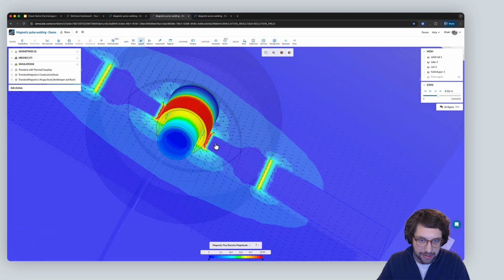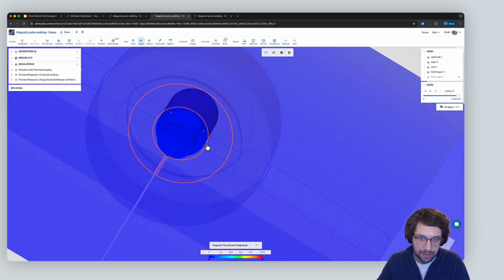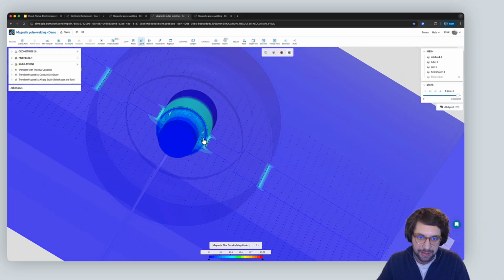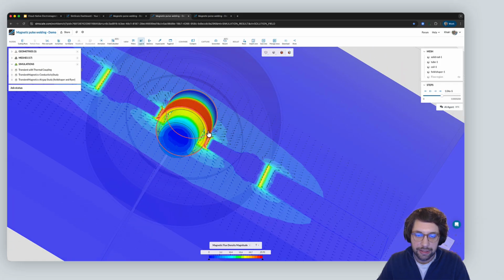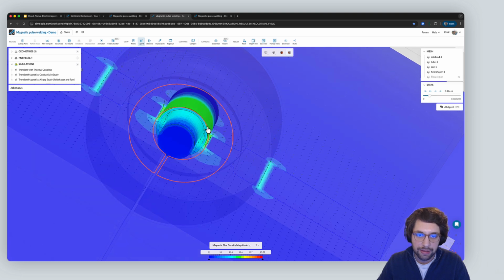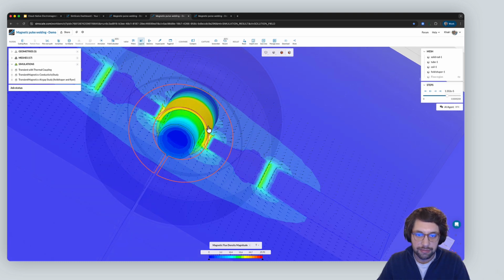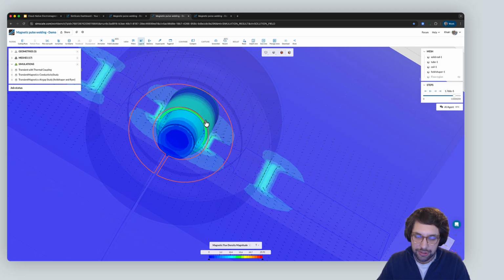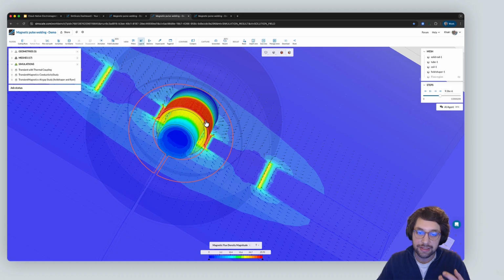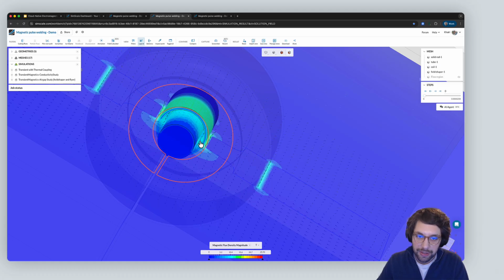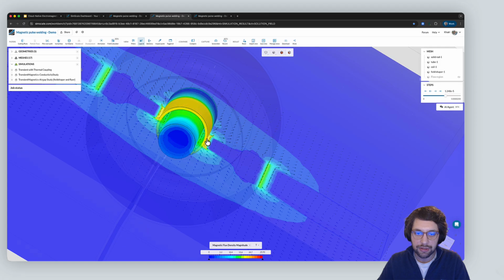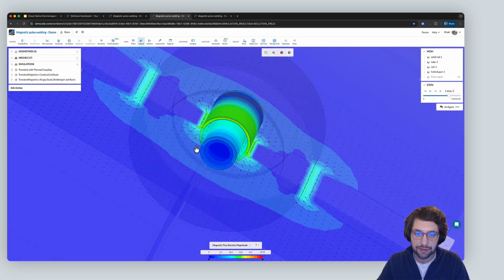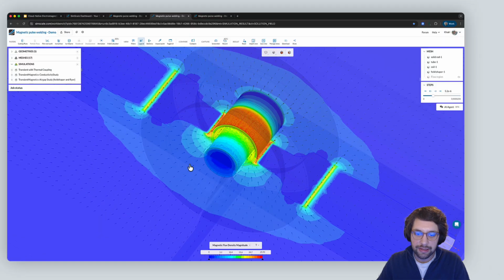We can also see that there is a significant amount of shielding between the flux density just before the flyer outer surface and then within the inner surface. And that is because of the additional electromagnetic fields generated on the flyer due to the initial magnetic field from the coil. We have eddy currents generated, which have their own magnetic field, which resists what tried to create it. So we have the shielding effects, which can also be termed electrical shielding in this case. Sounds good.